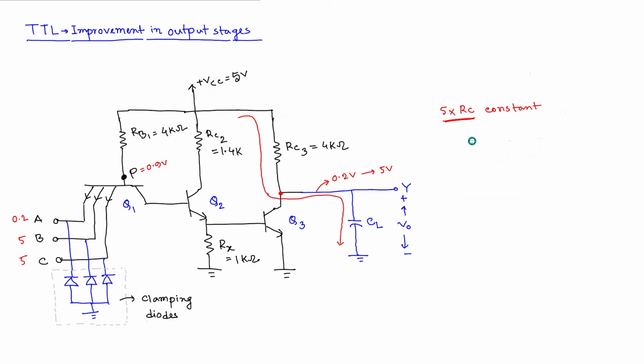Okay, but the problem is, if you do that, whenever this transistor is turned on, previously, in the previous state, we saw that this was saturated. As a result, this path was closed and current can flow through this path. In that moment, if you reduce the value of this resistance, a high amount of current can flow through this path, wastage of current, as well as that can also damage the transistor itself. So not a good idea.